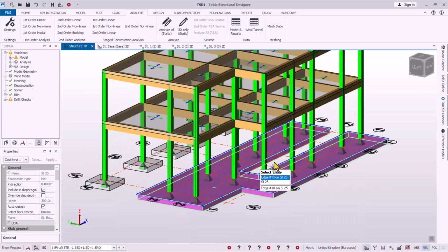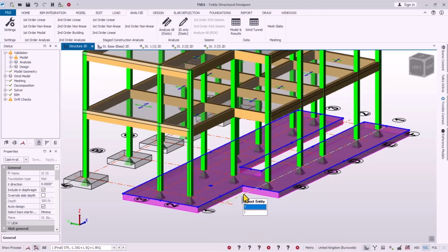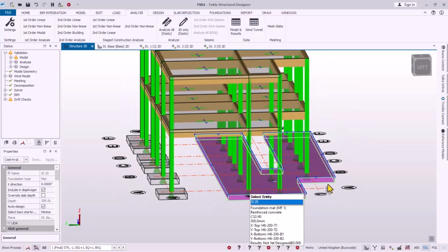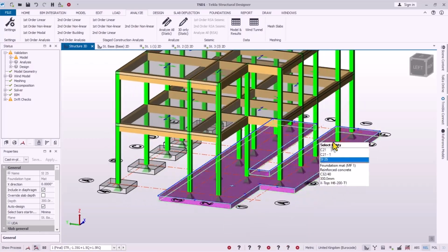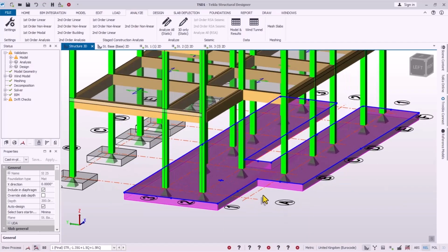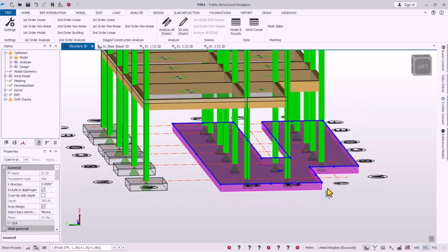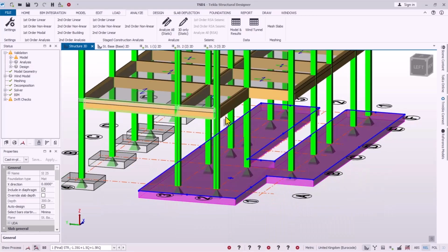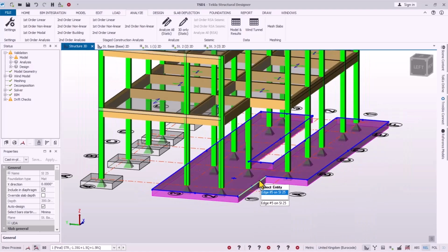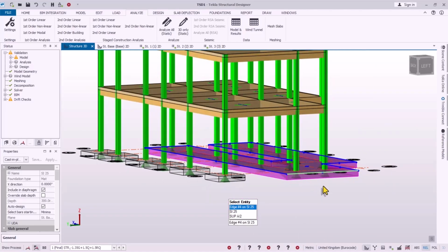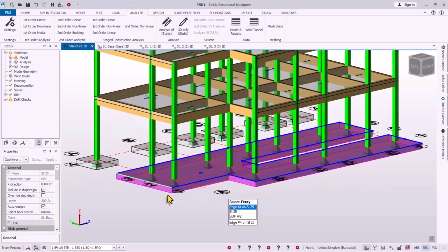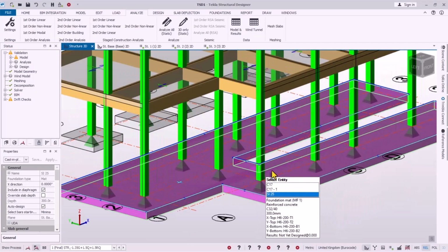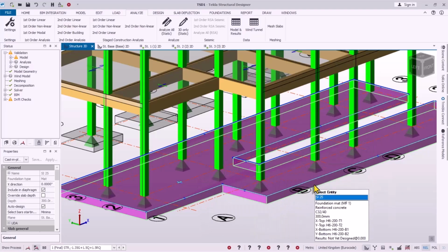So for the strip footing, just like when you are designing a flat slab, or when you are designing a foundation, a kind of floating raft or slab raft. This is majorly a slab raft, but it doesn't take care of the whole area of the building. In the case of a raft slab, it has to cover the whole area of the building, but this has just covered some part. That is why we call it strip footings.